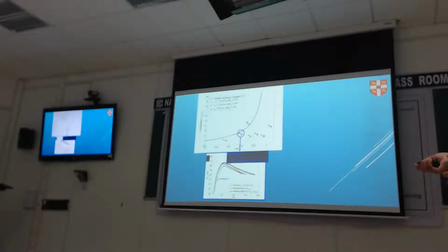So you can now plot the displacements we are getting with the axial load on the roof. And you can see whether you consider soil or just the residual, and if you include dilation, they're all coming pretty much the same. So the soil is not working that hard, and it doesn't have to.